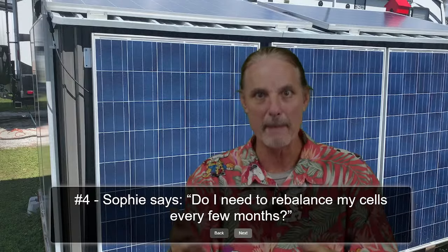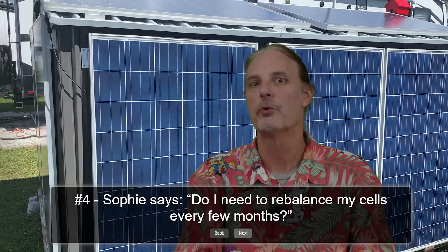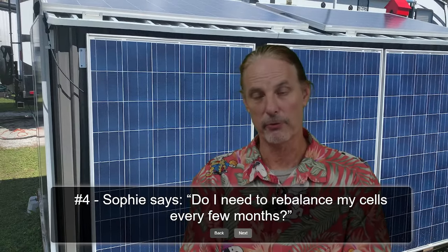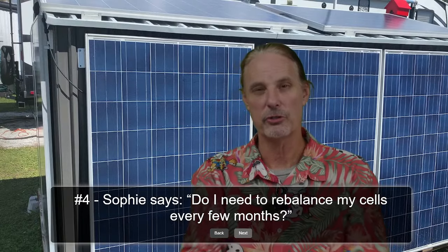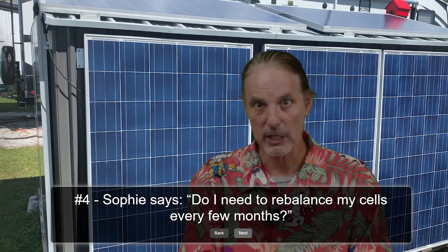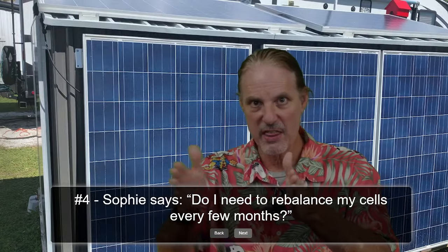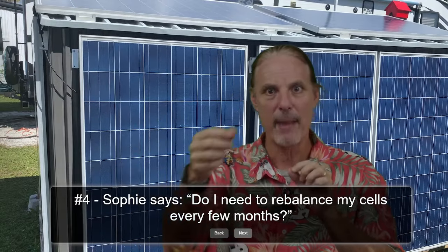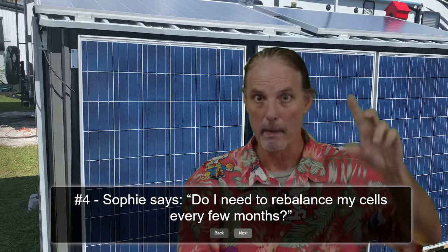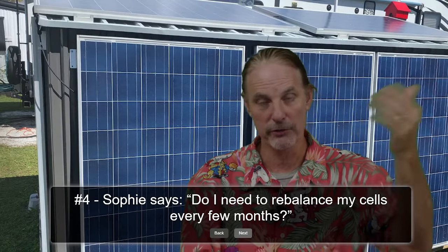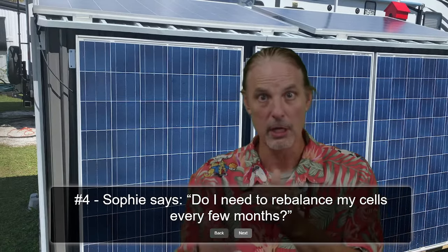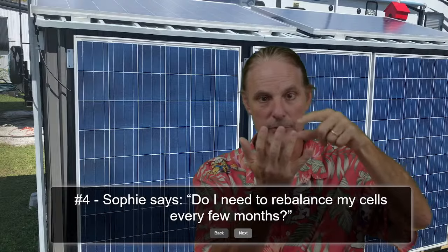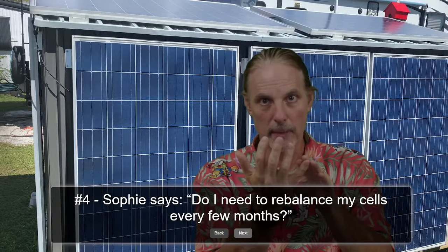Most likely, you're going to need to be slightly above that in order for your first couple of cells to hit, or slightly below that, actually, technically. It may start before that. So that would then start to do that balancing at that point, and that's when you need to stay in that balancing area long enough to allow that battery to, in a passive state, burn off that excess from the high voltage ones, and then replace that with new power coming in to charge up all of the cells again, and keep burning off on those high ones until all of the batteries are brought up to the right thing.